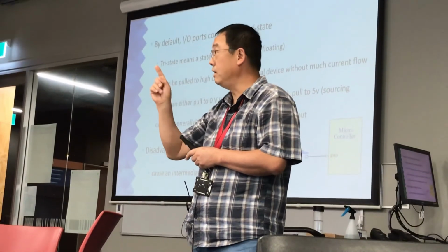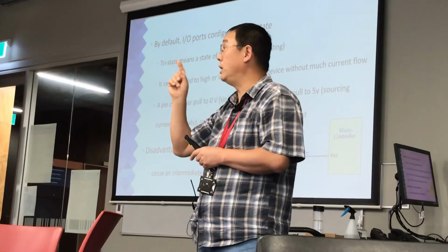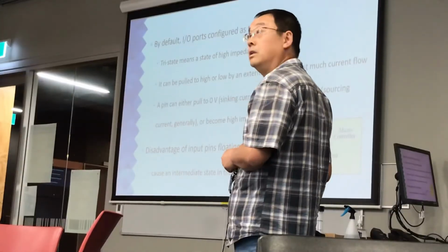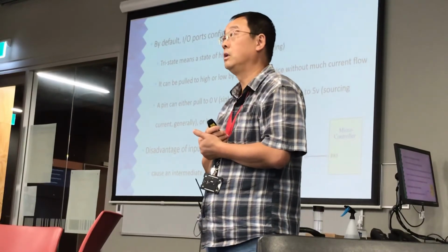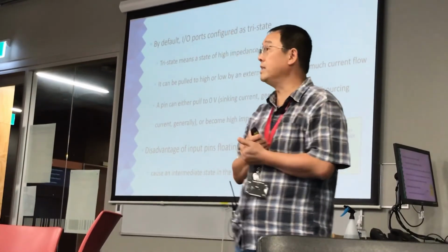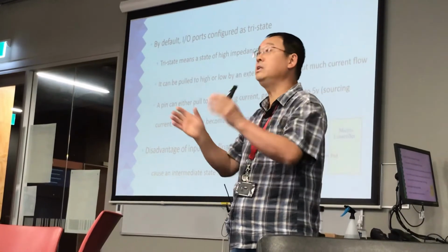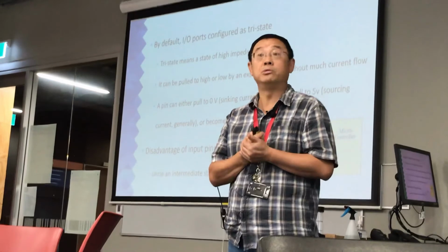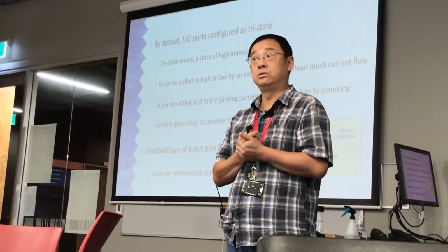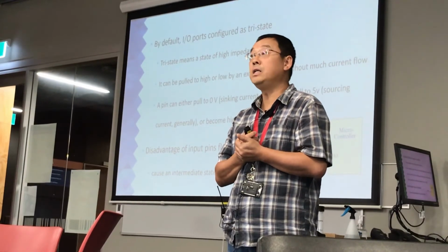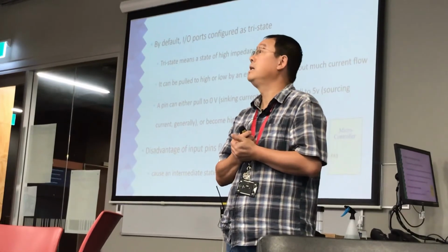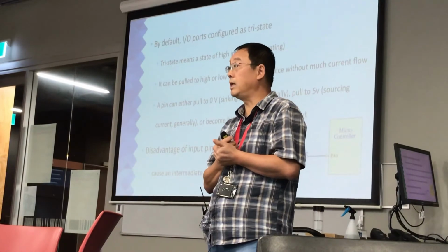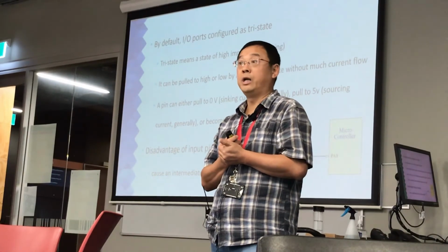Just remember, you cannot leave any microcontroller input pin floating, because static or anything can so easily change the input state. So do not leave any input pin floating. That is another thing you have to remember when you design hardware, otherwise you are going to have a big problem.